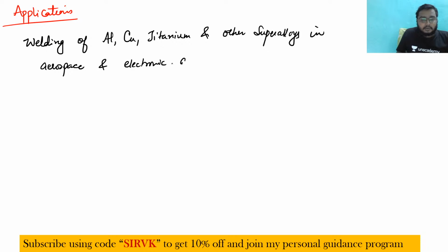In yesterday's class also I told you about electron beam welding. The applications of these two are closely related, used for very precision welding. Laser beam welding is a little bit cheaper than electron beam welding, so we use it also as a replacement for electron beam welding. Where we cannot afford it, that industry definitely goes for laser beam welding.